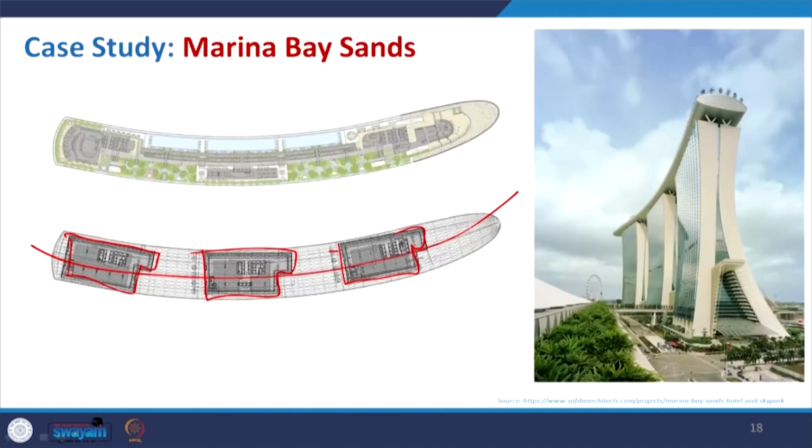So, in this example, what you get is that the core is not at the middle. The core is at the side. When we discussed different core positions, it can be split, it can be at one end like this. So this is very simple, and because the story count is not that much compared to the other buildings, the system is again the core along with the frame structure, but the main challenge was to take the load that was calculated and that is resting on top of it.